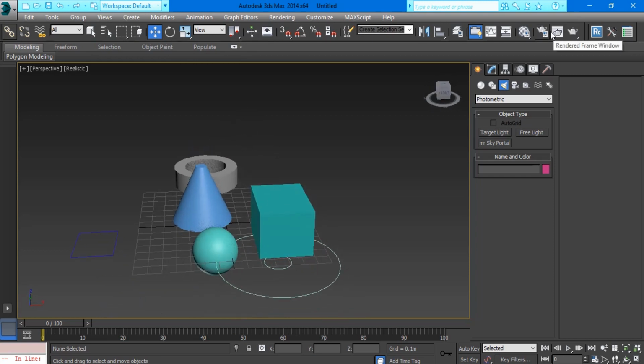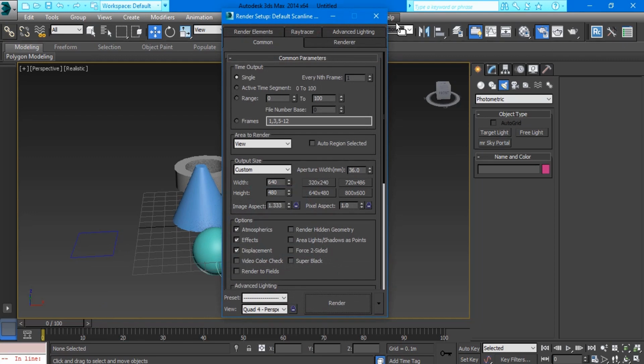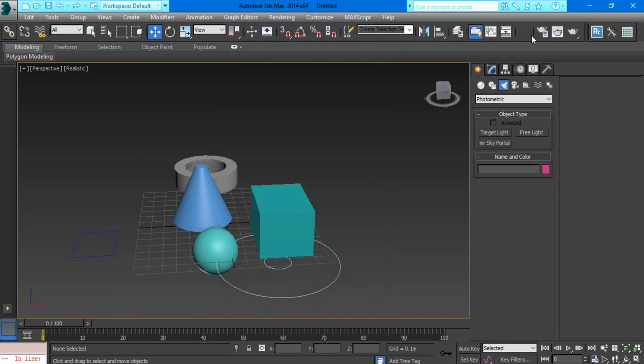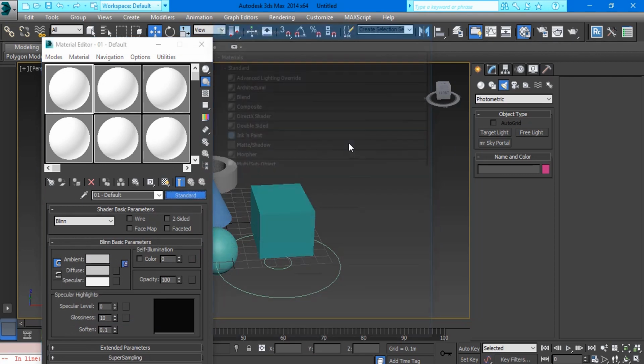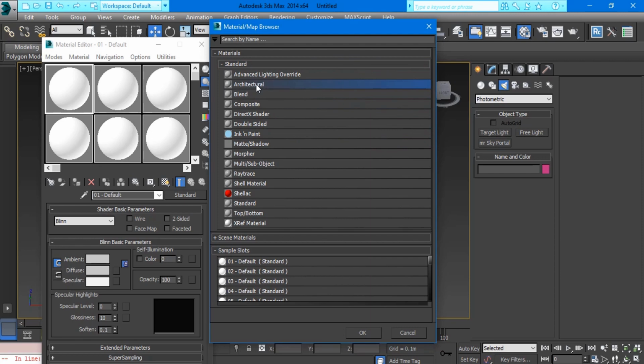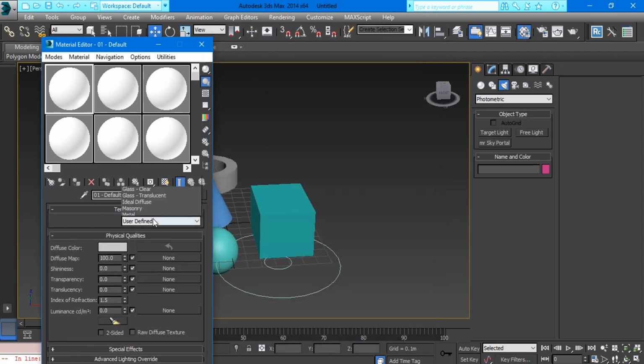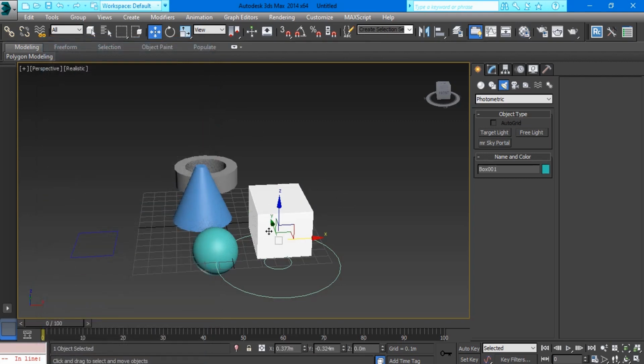So if I wanted to create a material, I would just go here, go to standard, and go to architectural, and then just use probably a stone, and just add it here. And then I know I don't want it anymore, I'm just going to press Control Z, or if I want it back, I'll press Control Y. So these are various shortcuts which you need to understand.